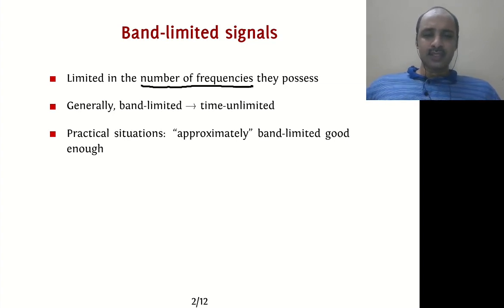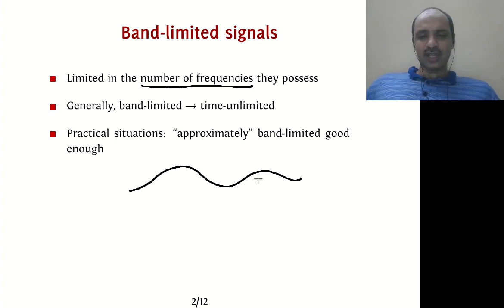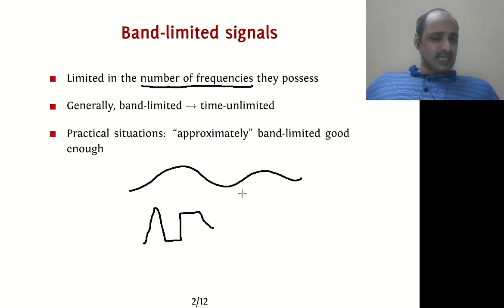But more importantly, signals that have very gradual movements, not very high slopes, and which change very slowly, generally tend to have a lesser set of frequencies. But signals which have abrupt movements, discontinuities, or even points of inflection, these signals tend to have a higher frequency content. Why is this the case? This is something I'd like you to think about, but whenever there are abrupt changes from continuous behavior, sinusoids are not good candidates to approximate these. In fact, if you remember what you've seen in signals and systems about the impulse function, an infinite number of frequencies are required to produce sharp transitions.